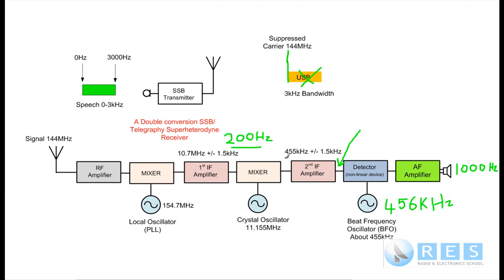If you switch from single sideband to CW and you have a CW filter fitted, you notice a massive reduction in noise. That's why CW is so good at communicating through difficult HF conditions, because of the low noise in the receiver due to the receiver's very narrow bandwidth.